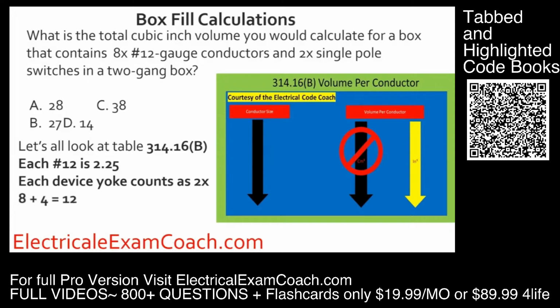We know we have 8 original conductors, and we only have 1 size wire, so it's going to get grouped with the 12s. Each one of those devices counts as 2, so we end up with 4 more number 12s, which gives us 12 12-gauge conductors. Now we do our math, we end up with 27 cubic inches, and we select B.